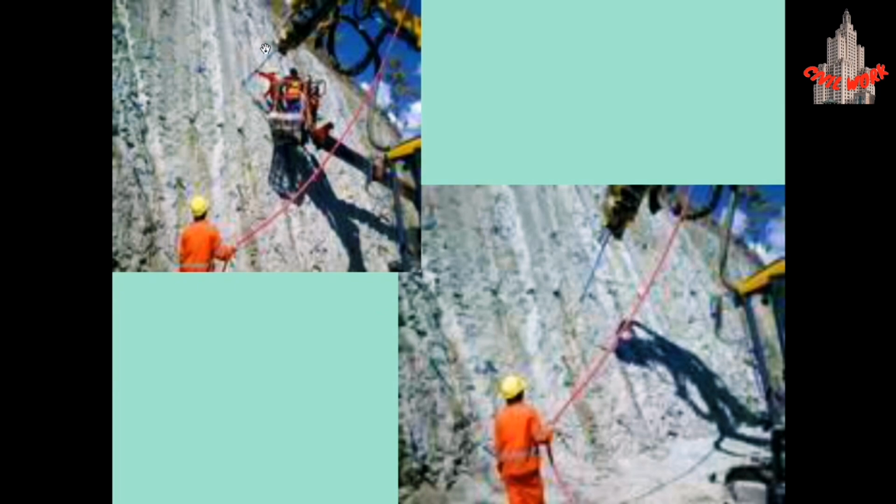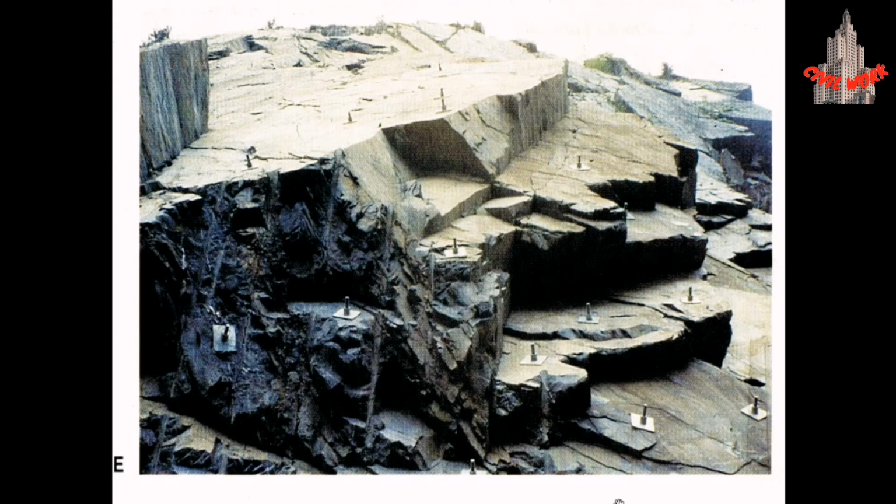First of all, we drill a hole in the rock. We can also provide grouting there. First we have to drill a hole and fill it with shotcrete. This is how the rock bolting is done. Here we have the rocky strata, which is prone to weathering, and after bolting it from different places, it will become a stable area which is less prone to erosion and weathering.